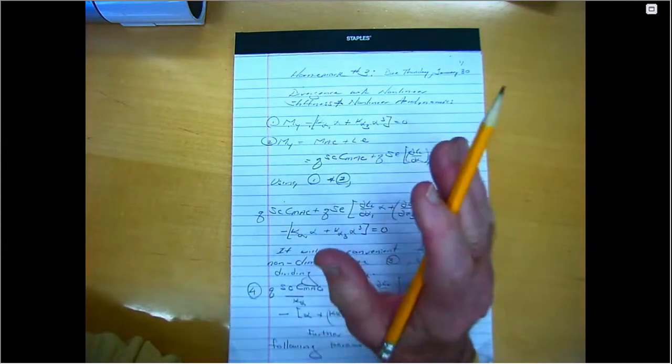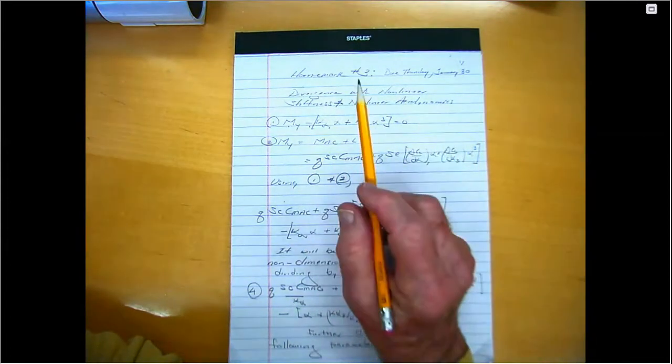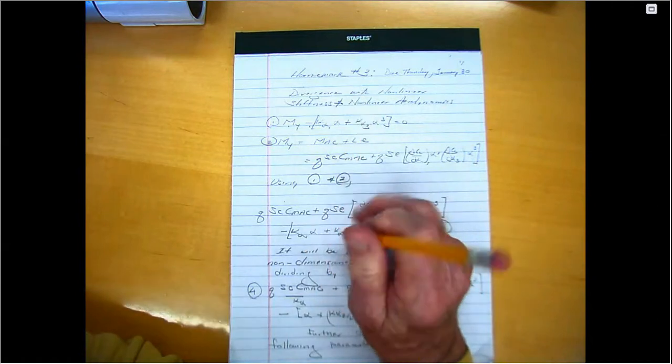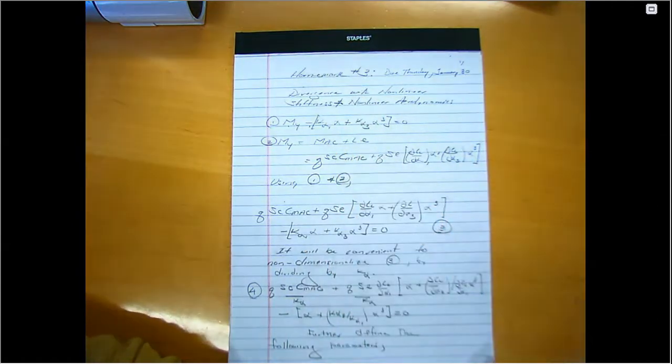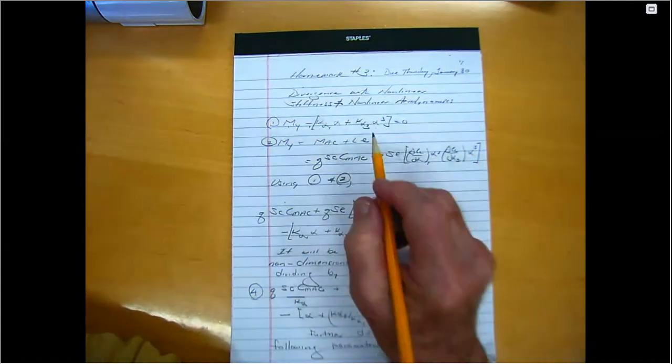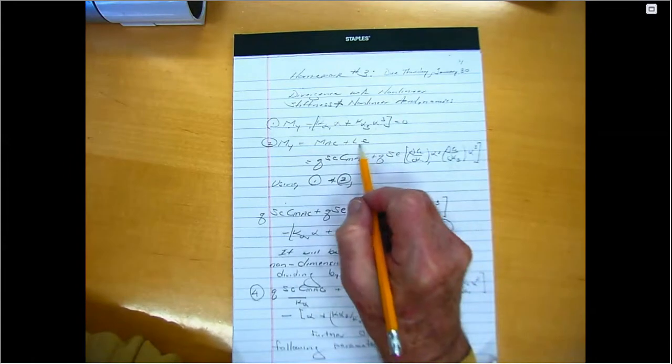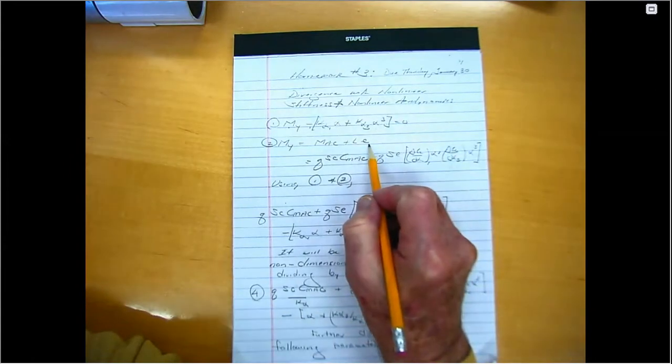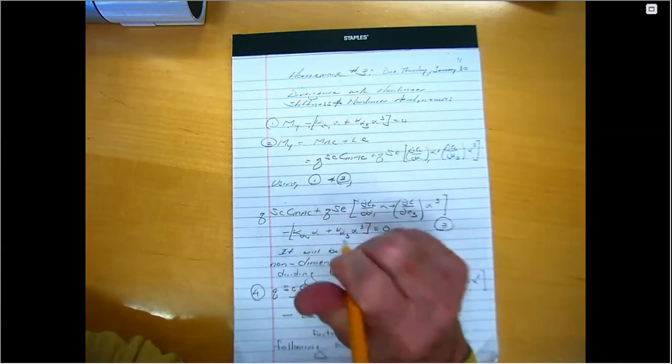That's the important thing about the aerodynamic center. By definition, it's the point about which the moment due to the pressure distribution does not depend on alpha, plus the lift times the distance from the aerodynamic center to the point where the springs are fixed, otherwise known as the elastic axis.